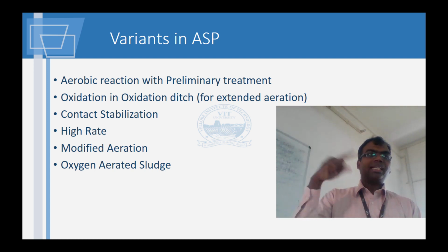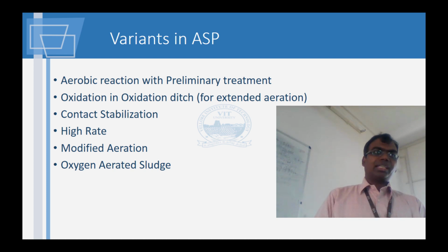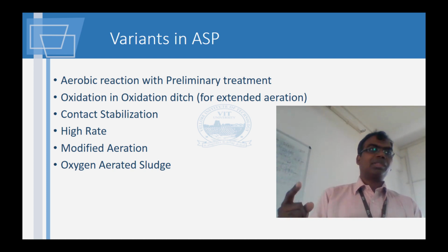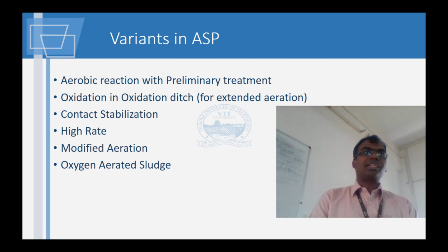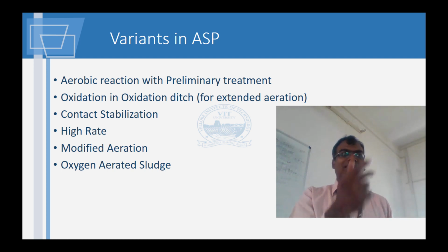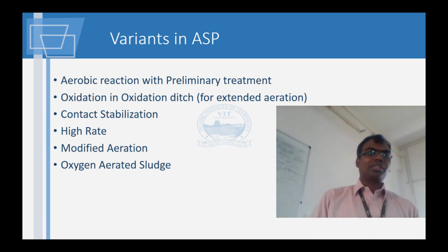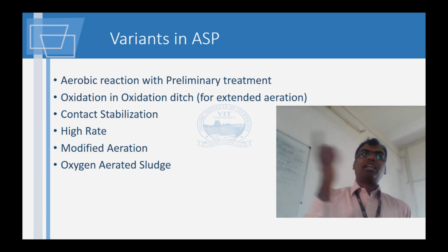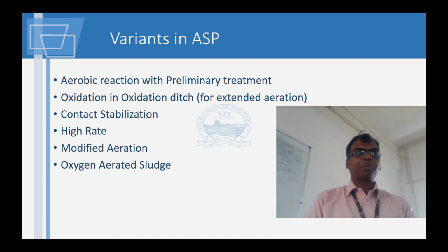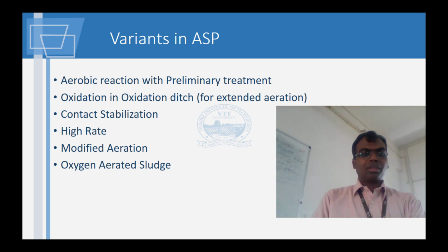Here you saw some paddles rotating for aeration. So sometimes they can have compressed air and then compressed air and paddles, because this will be just like your fish tank. In the fish tank, you will have a stone-like thing which, if you put compressed air in, it diffuses with bubbles. So that is one system of aeration, but there you'll have pipes of compressed air with the air diffused, and then they'll also have paddles to make the air mix more thoroughly with the liquor.